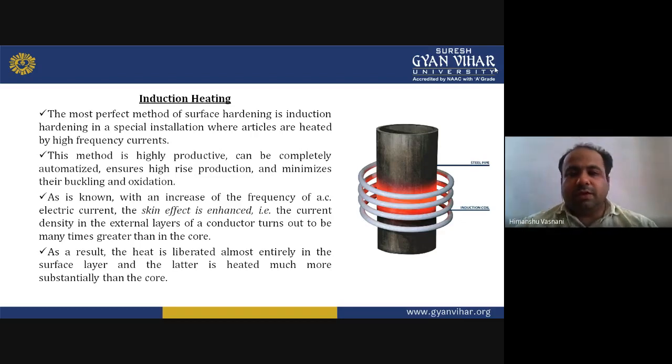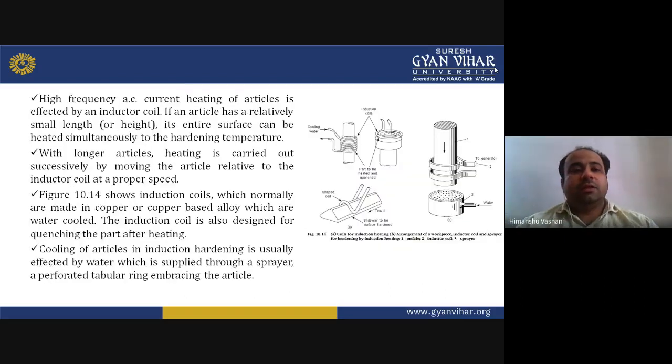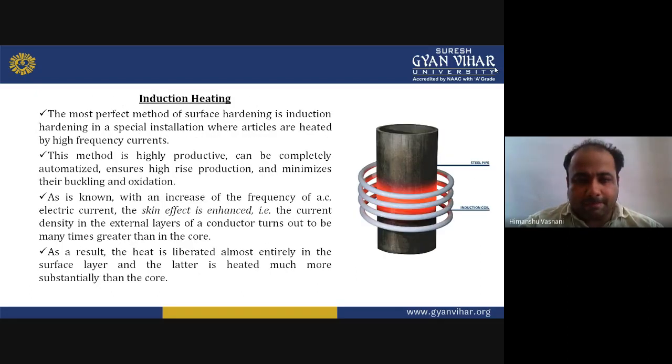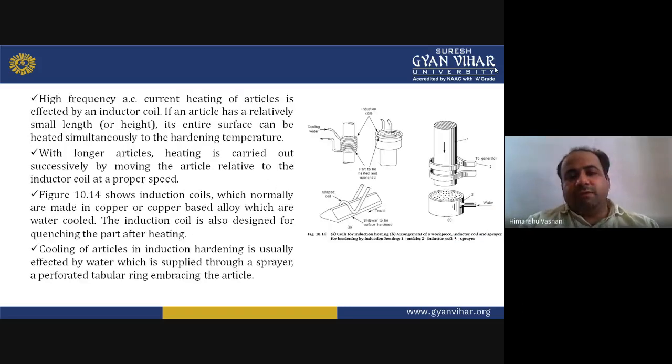Okay, the coils, the heat is liberated almost entirely in the surface layer, and the latter is heated much more substantially than the core because it is getting the AC current in this. So high frequency AC current heating of particles is affected by an inductor coil.